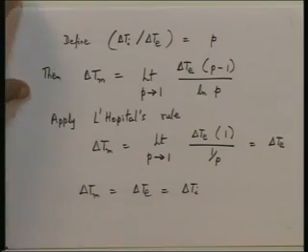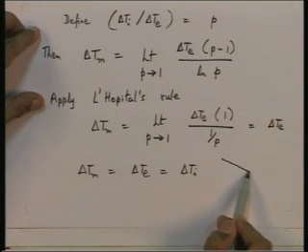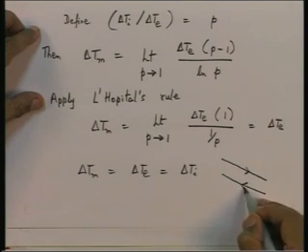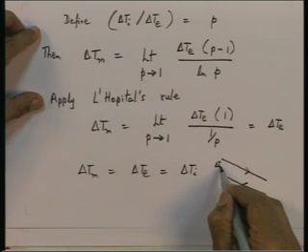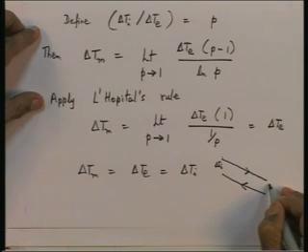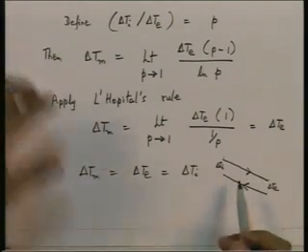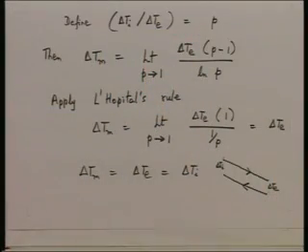And in fact, in this particular case, what really happens is the following. What we really get is the temperature profiles on the two sides are two parallel lines like this. This is on the hot side, this is on the cold side, this is delta Ti, that is Thi minus Tce, this is delta Te, which is The minus Tci. And if you have two parallel lines for the temperature profiles, it follows that delta Tm must be equal to delta Te must be equal to delta Ti. That is really what we are getting. So, for the special case, the temperature profiles tend to be straight lines, two parallel lines, and delta Tm becomes equal to delta Ti or delta Te. So, this is one special case of counterflow worth talking about.